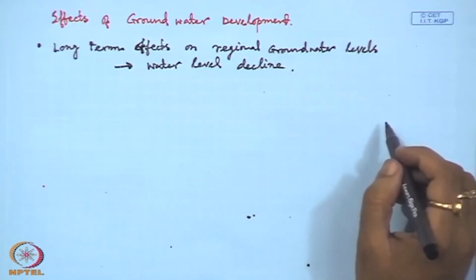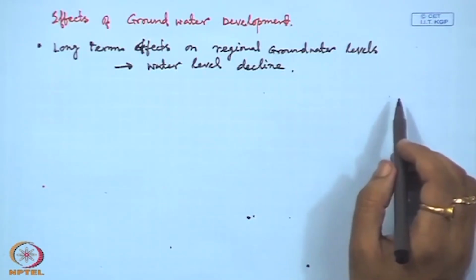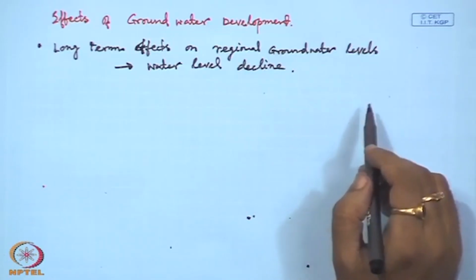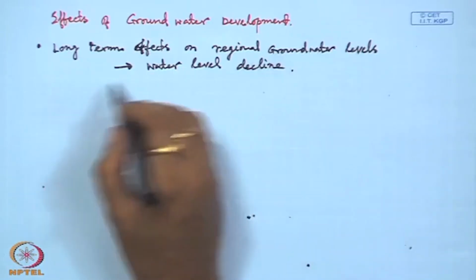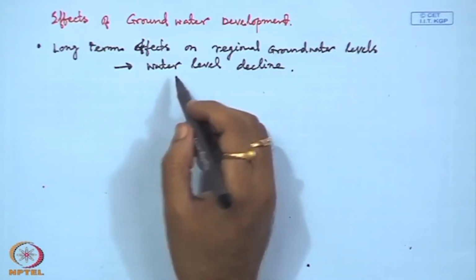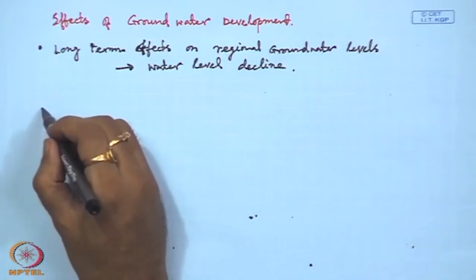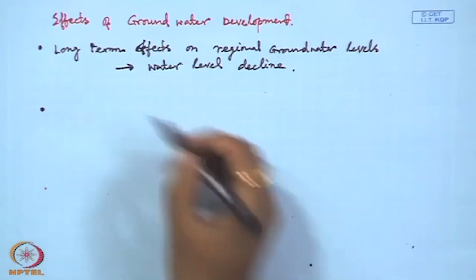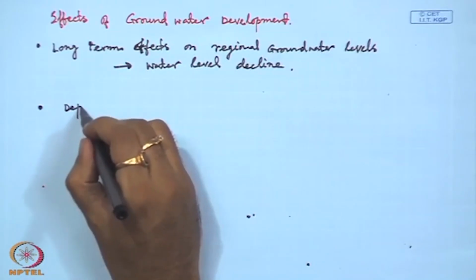As long as water is mined, that is withdrawal of water in excess of the induced recharge plus the reduced groundwater discharge from an aquifer, the water levels or potentiometric surface will be continuously lowered in elevation on a year by year basis, and this will create problems, and this problem is due to groundwater development. Second is depletion of surface water.